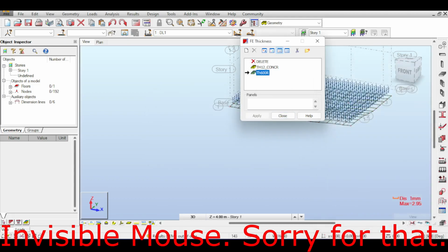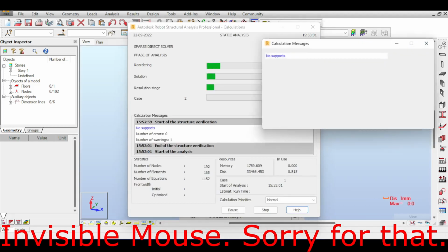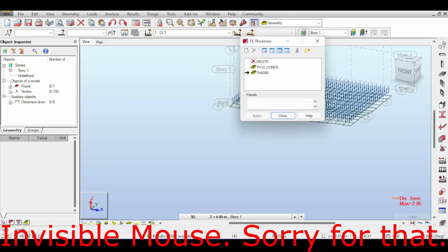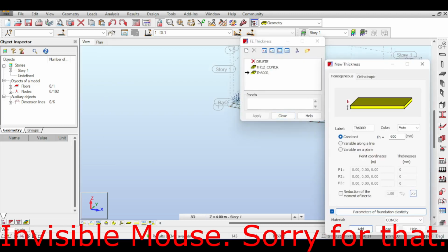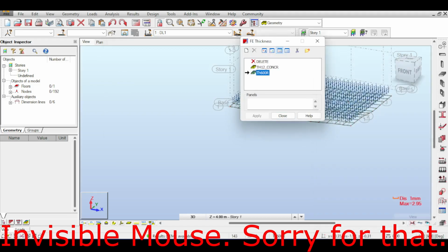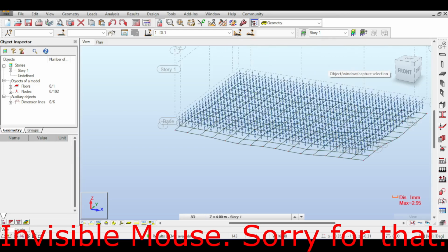I will be addressing this maybe later when you have full structures, because there is nothing pushing in the X and Y. Well, it seems that this placeholder 1 that I have added in KX and the placeholder 1 that I have added in KY was good enough to hold the structure in place, and now there are no instabilities. So that's the first thing I wanted to talk about.